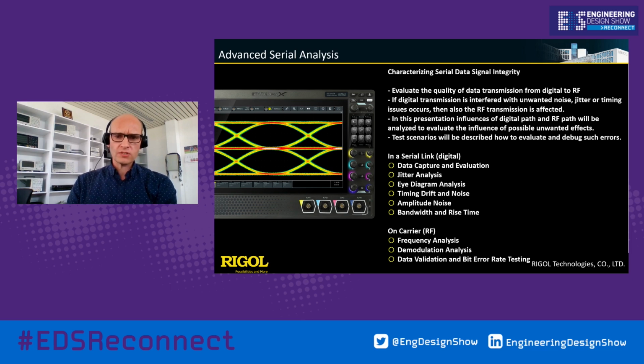Afterwards, we want to focus with our test devices on the RF carrier analysis. For example, the frequency analysis is quite important then, and we want to focus also on the demodulation of the digitally modulated RF carrier. Last but not least, we want to make the validation and do the bit error rate testing to fulfill the specification of the device under test.